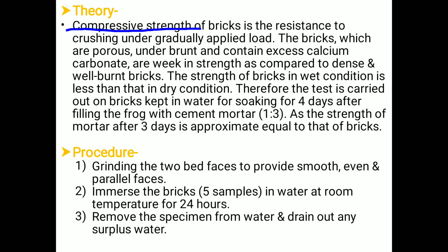Next, compressive strength of the brick is the resistance to crushing under gradually applied load. Bricks which are porous or underburned and contain excess calcium carbonate are weak in strength as compared to dense, well burnt clay brick. The strength of the brick in wet condition is less than that in the dry condition. Therefore, the test is carried out on brick kept in water for soaking for 4 days.